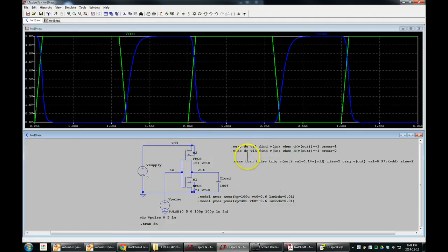We would make our measurements on the second inverter. The first inverter would drive it. And now our pulse source with these absolutely sham waveforms doesn't affect our measurements nearly as much. We go from fanciful world, ideal spice world, to waveforms that are much more realistic, and so on. That's how we do it.